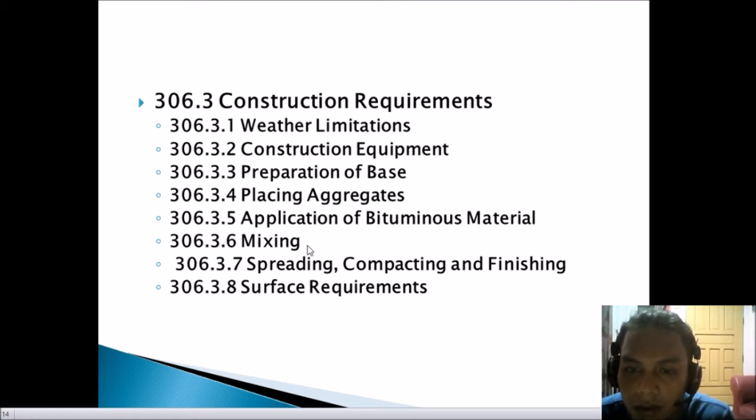When the compacted thickness of the road mix surface is to be more than 50 mm or 2 inches, the mixture shall be split from the windrow and compacted in two layers. The first layer is to be compacted before the second layer is spread. The material shall be spread by a self-propelled pneumatic tire, blade grader, or a mechanical spreader of a type approved. After the material is spread, the surface shall be rolled. Rolling shall be parallel to the road center line and shall overlap with the outer edges of the road.